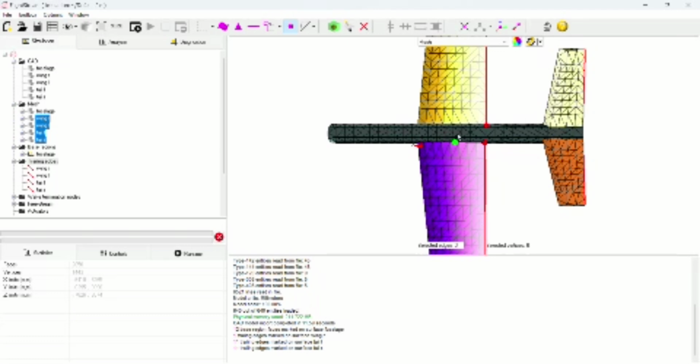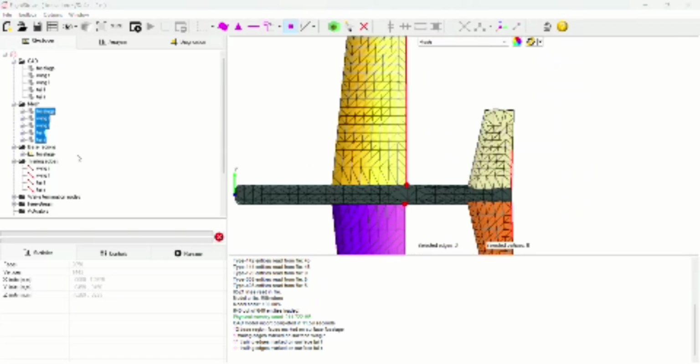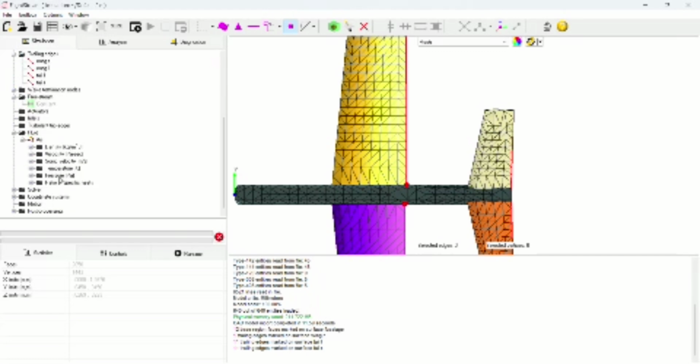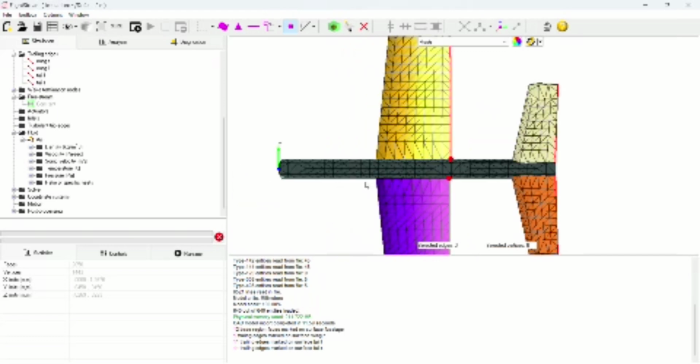After wake termination nodes are detected, you also can put in other boundary conditions such as free stream and inlets or turbulent edges. Here free stream is a constant, so that is not anything which we should mess around with. The fluid which we'll be simulating on is air actually, and again the properties of air also can be manipulated based on the parameters you want. So we have density, viscosity, sonic velocity, temperature, pressure, and ratio of specific heats.